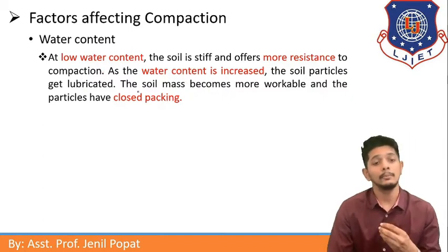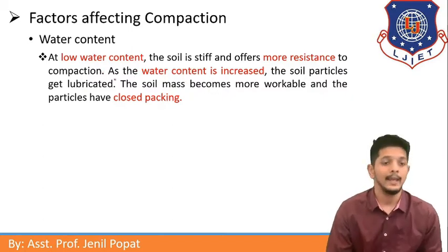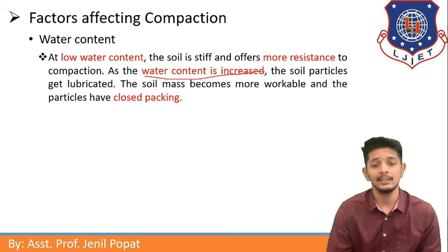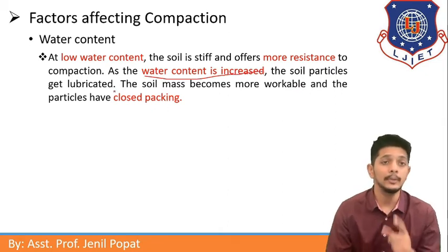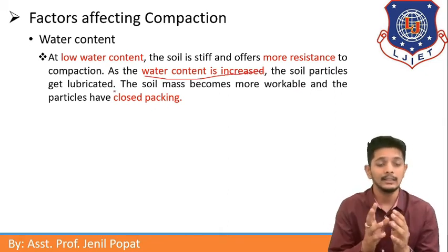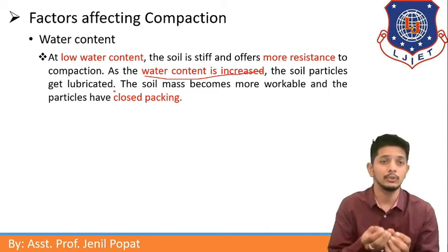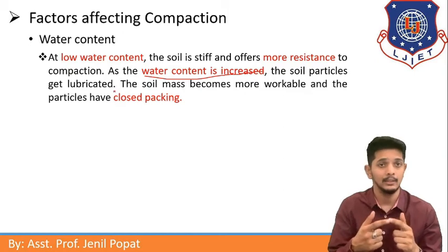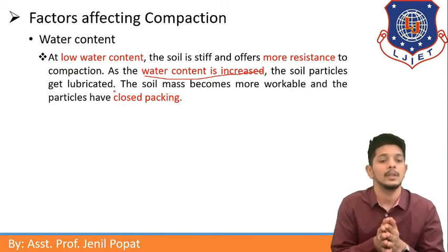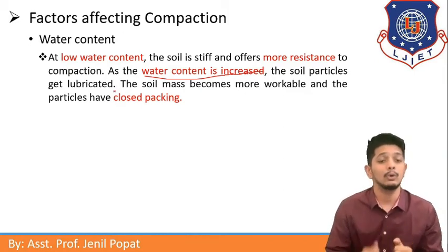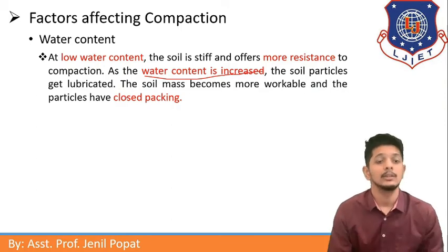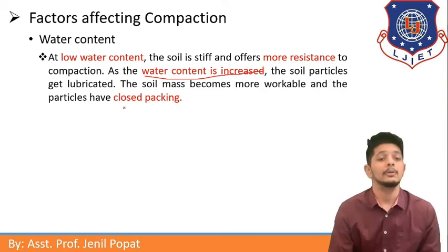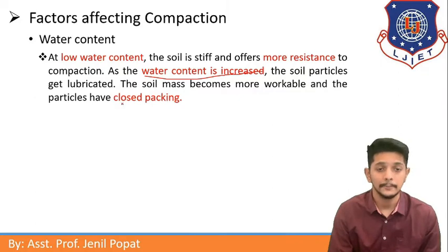But if you provide more water content, as the water content is increased, the soil particles get lubricated. So soil particles are in movement as you give water to it. The soil mass becomes more workable, so it can flow, and the particles have closed packing due to that, so compaction will be more effective at higher water content.